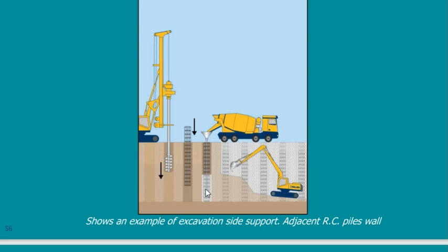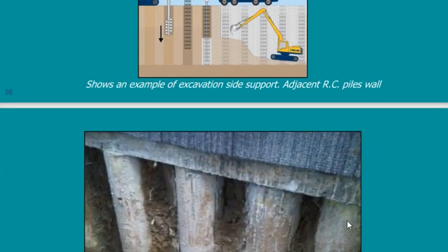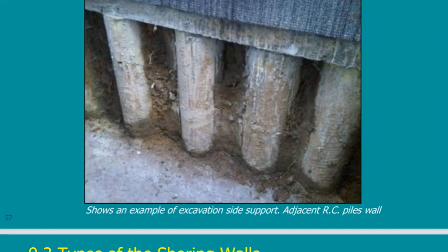So when I finish, I will find that I have piles with gaps in between. Maybe this shape will let you understand what I mean. This is a pile, this is a pile, and this is a gap. Soil here is not falling because soil can carry itself in between these piles.